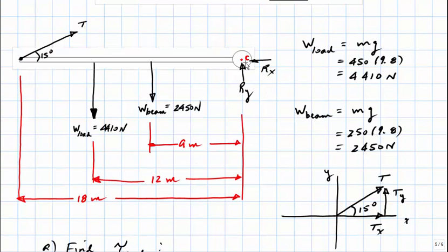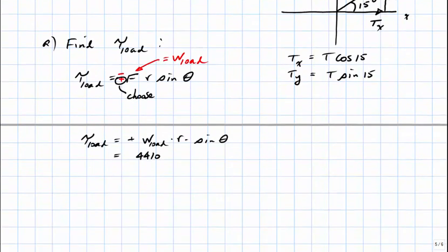Now, of course, this is the center of rotation, and the contact point for the load is right here. We can make a little dot there, and if we connected those 2 points, the length of that line segment is the moment arm. Now, of course, we can see that the length of this line segment simply equals 12 meters, and that is the value for R, which is the moment arm.